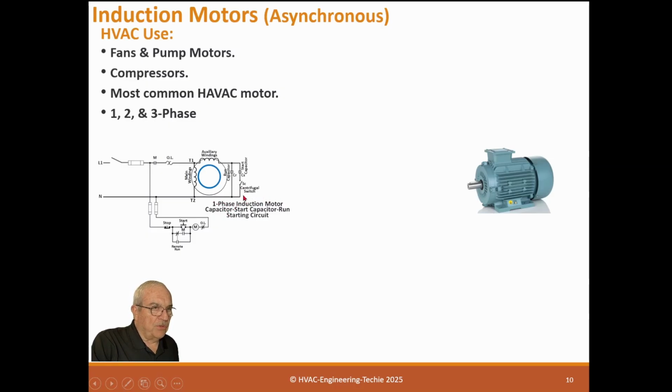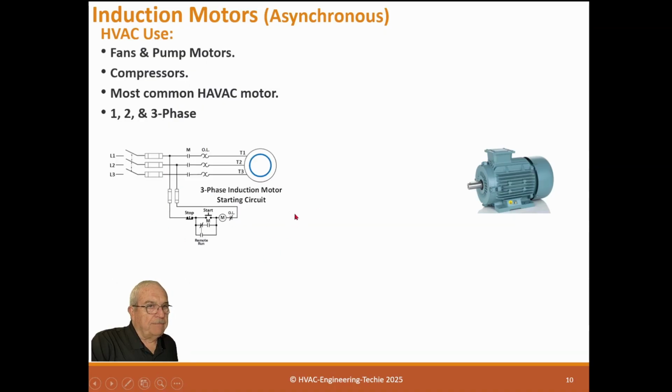For capacitor start, you have a startup capacitor and a switch, which is a frequency switch or a centrifugal switch. As the motor starts up, this winding is in start. This capacitor goes online and starts with that winding. As it gets up to speed, that switch opens and that winding goes dead, and the run winding takes over. Same thing for 3-phase, except they don't need the start capacitor because they have 3-phase.